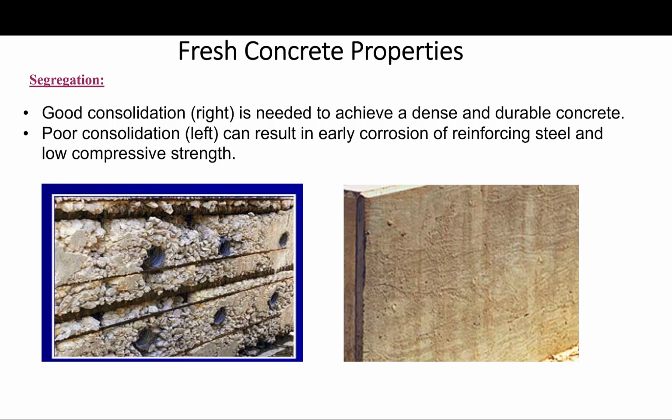So as I said, freshly mixed concrete must be relatively easy to transport, place, and finish without resulting in harmful segregation. So we need a workable mix. The material has to be almost fluid-like, and it has to be cohesive. So it is really a qualitative property that incorporates consistency, ease of flow, and cohesiveness, meaning it does not segregate.